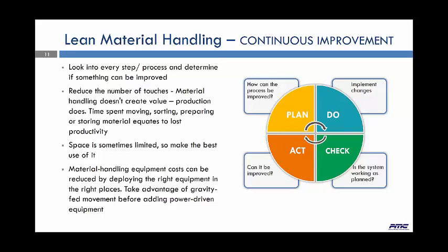Again, the key takeaway from this material handling presentation here is to try to minimize the distance a part has to travel inside the facility, right from when you receive it at the dock all the way to the assembly line, and sometimes back, especially the empty containers coming back into the warehouse and going out to the trailer again. So you map out all the distance for each. Sometimes, I don't want to say for each part, but if you look based on the route, you'll be surprised that they travel a long distance from the time they get in to when they leave the facility.